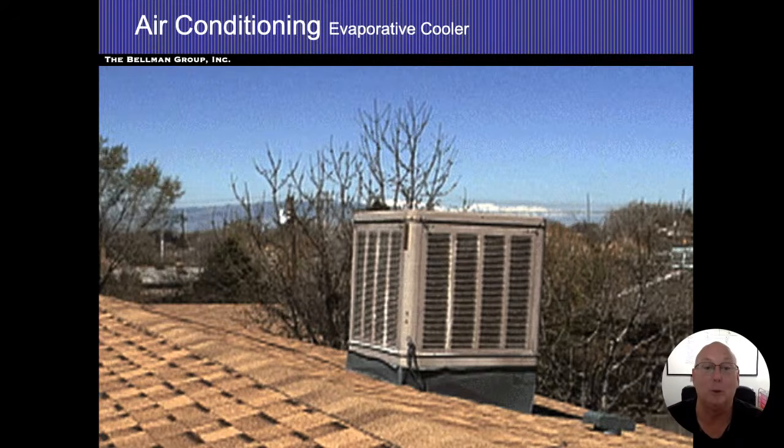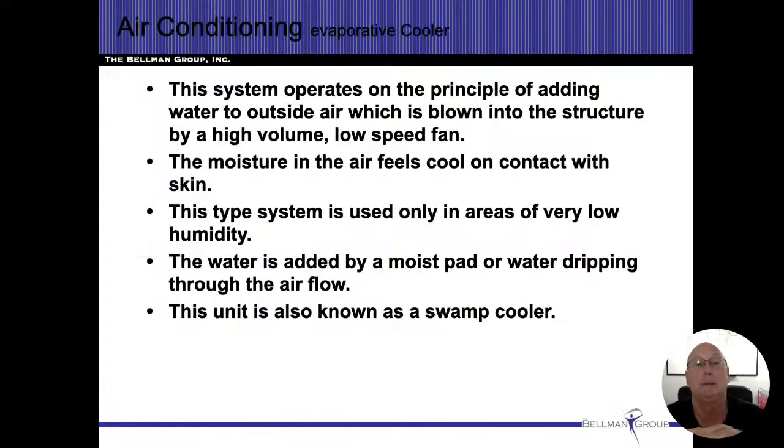So large amounts of air. The windows are open. Blow humidity in the house. The humidity lands on the object. Dry climate causes it to change to a gas. When it changes to a gas, it absorbs the BTUs, and this actually works very well. All right. The system operates principally on water and outside air. We just said that. The moisture feels cool on contact with the skin because it's evaporating. It's only used in very low humidity. Water is added by a moist pad, water dripping. Same type of humidifiers that we use in our own houses, and then more of a nickname than anything else, they call them swamp coolers. You'll hear that as well.